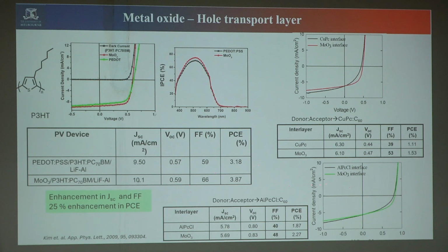So in future, for real fabrication devices, we don't prefer PEDOT:PSS; we only prefer a metal oxide interlayer. But for testing purposes, when you find a new material, for testing devices and making short-term devices, PEDOT is very good because it's readily available. We can easily spin coat it. For processing, it's simple, but in an actual production case, we'll go for the metal oxide interlayer.